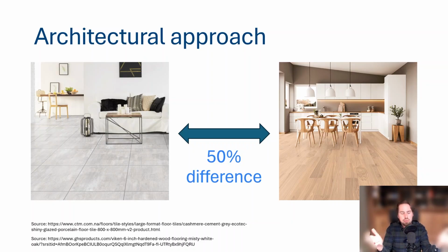So when you have a high imbalance in extraction, you're extracting more heat than injecting, and you rely on passive cooling with your floor to regenerate, to put heat back into the ground, having a hard wooden floor will actually prevent that, because there is quite a lot of resistance for the heat to travel from the air to the floor cooling system.